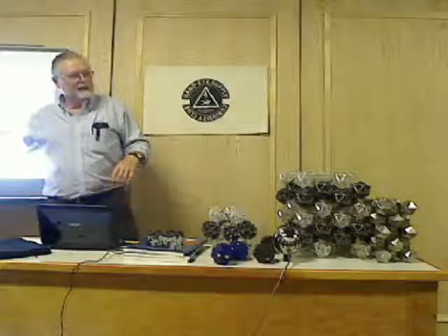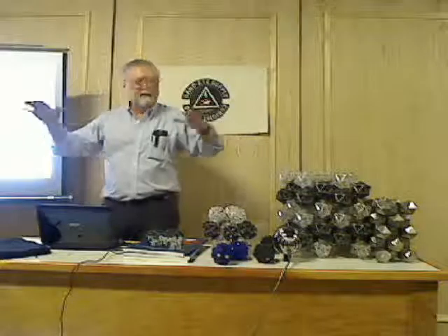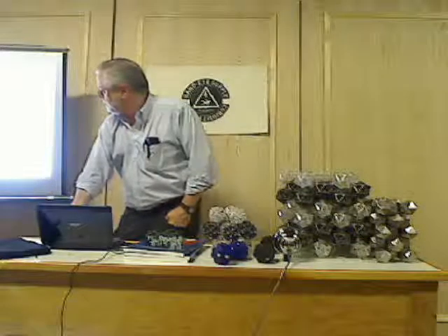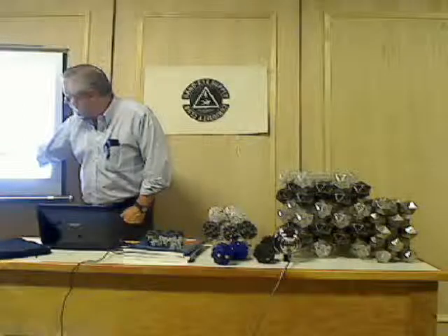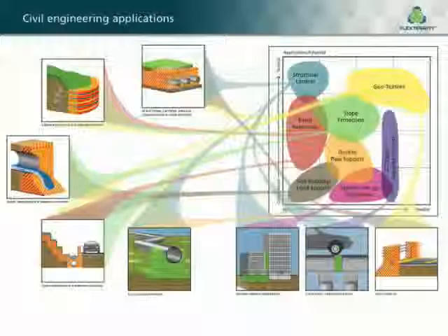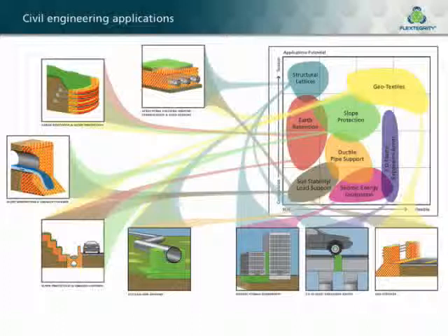Here's a depiction of how buildings in earthquakes, because of their different size and different mass, sway at different periods, and then they collide against each other. And that's what causes them to break apart. Well, you could pick up a lot of that resonance and dissipate it within these kinds of structures.